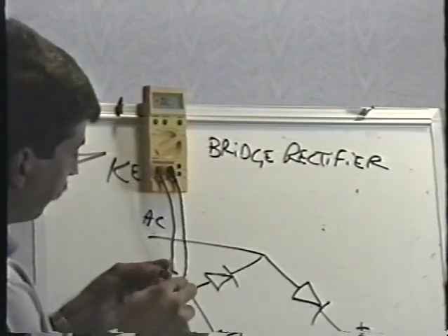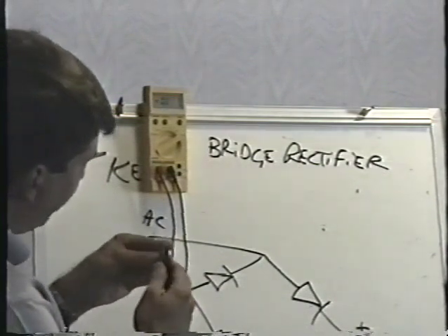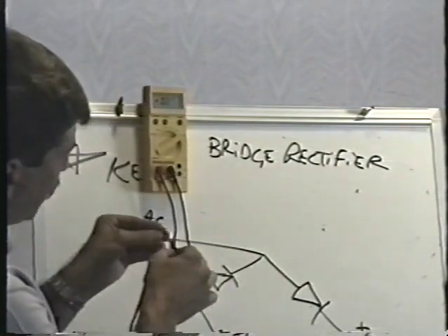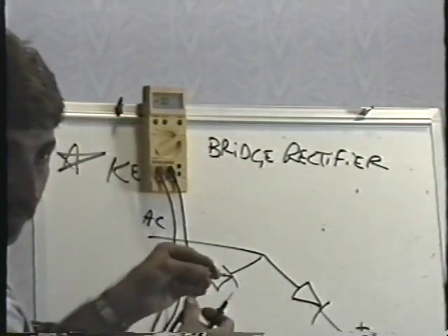Whoops. 0.001. I'm not faking you out here. Let me just hold it up clearly so you can see that I'm not. That diode is shorted out, isn't it? That one diode is shorted out. Since you can't get in here to repair it, obviously the whole unit's bad.